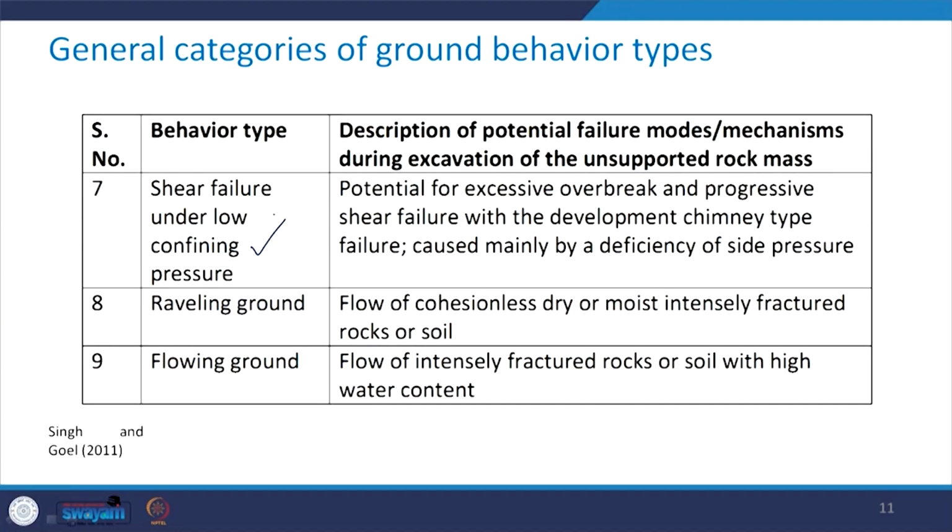This has potential for excessive overbreak and progressive shear failure, along with the development of chimney type failure, and this is caused mainly by a deficiency of side pressure.